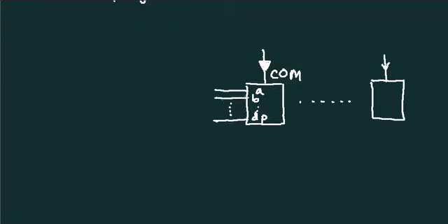All the A segments of all digits will be shorted, made common. All the B segment lines of all the digits are connected together. Similarly, all the rest of the segment data lines are connected together. So, all these 8 lines are in parallel. Ultimately we get only 8 lines up to the microcontroller. So, these lines will go to the microcontroller.